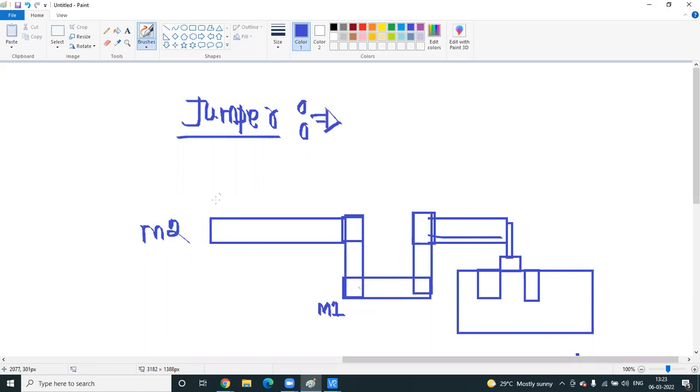Fabricated means your charges are present here, in the M2 layer. This is already fabricated. So if you use a lower metal, these charges have a path, because these charges are what cause the damage. Path means it is also coming here, and it will go. And we are not saving your antenna effect.